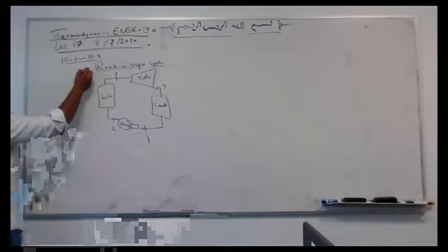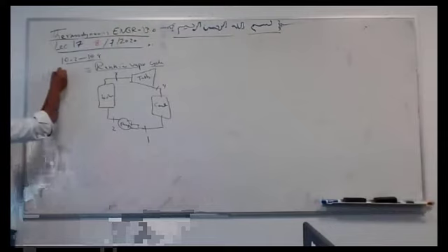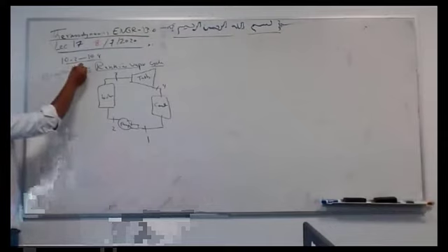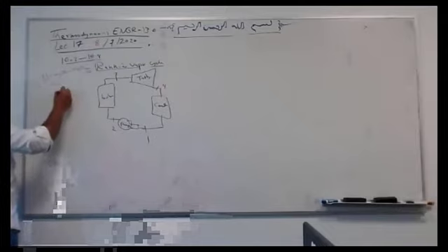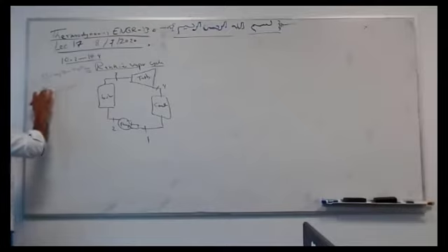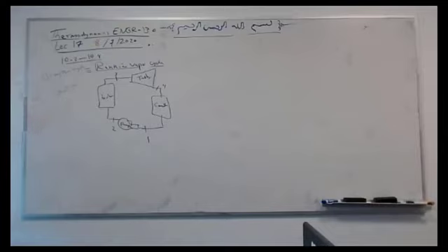But the difference is, the Brayton cycle was for air, an ideal gas, generally. It can be an ideal gas, can be air, can be refrigerant 134A, can be CO2, can be any ideal gas. Rankine, nope.